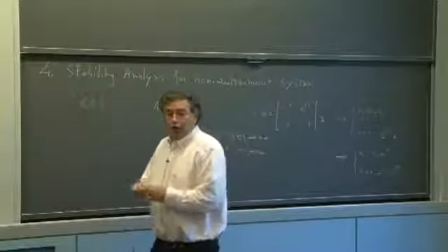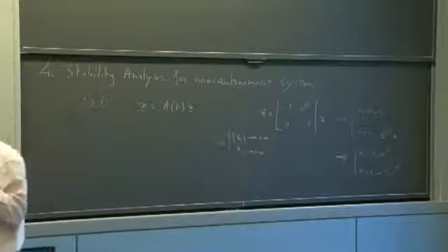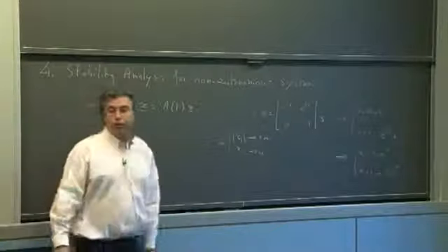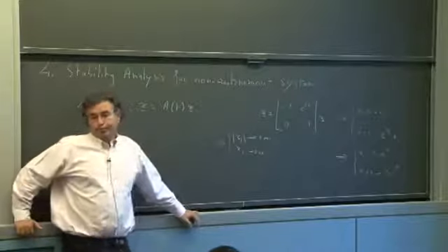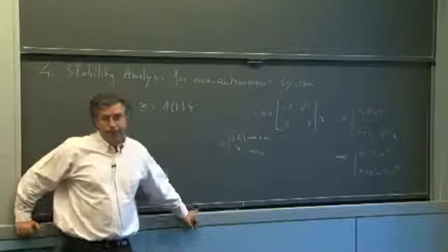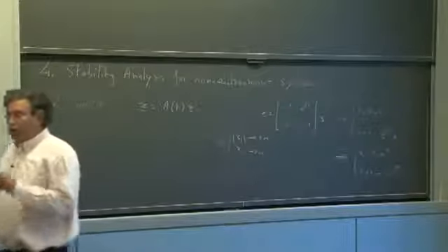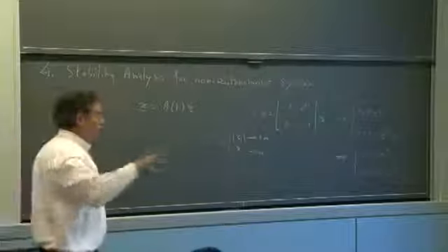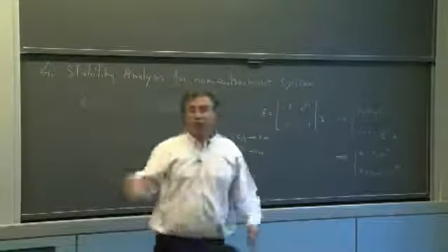Here we have a very simple system where the eigenvalues not only are in the left half plane but are constant, but the system blows up. So it's not true that if you take a linear time varying system, you just have to look at the stability of each of the linearizations and you'll be fine.